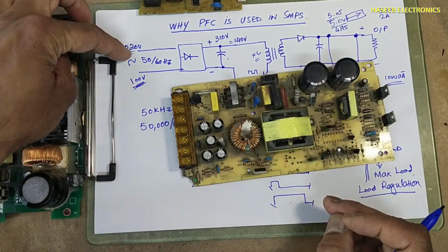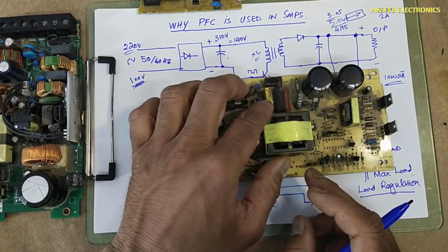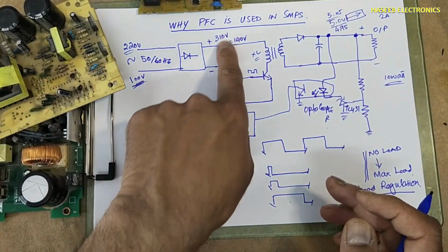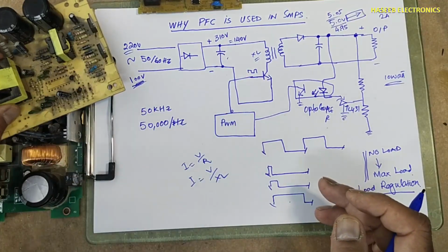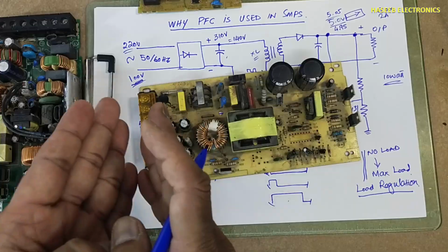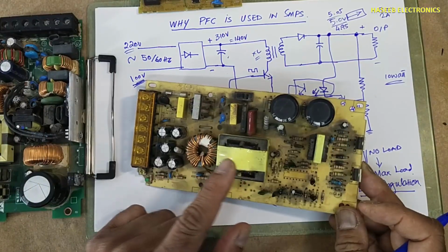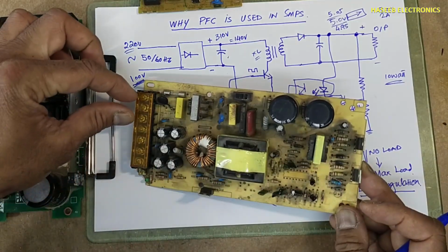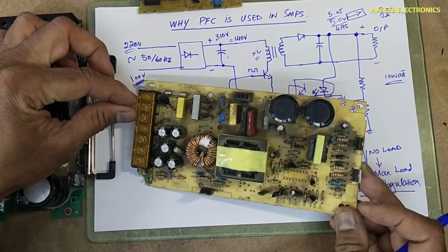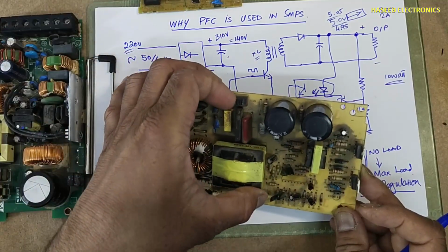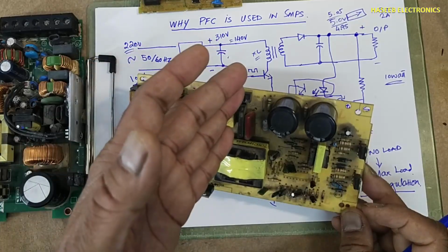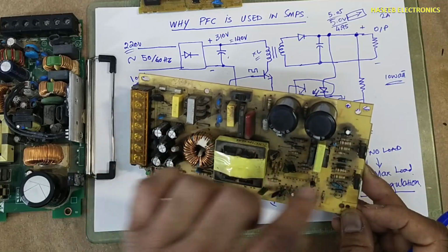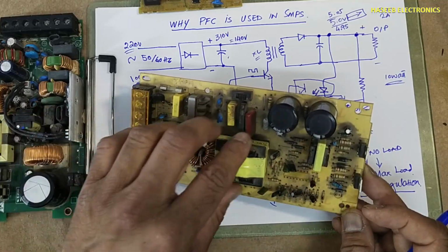If the voltage drops below 185 volt, maybe this power supply will lose its line regulation, because line voltage is dropped. Why? Because we are taking 250 watt output. So in that case, this IC will fail to regulate the voltage due to line loss. For that purpose, this switch is used here. If we are operating at 110 volt, at that time line voltage will be regulated at DC rail. So we will take regulated 250 watts output.